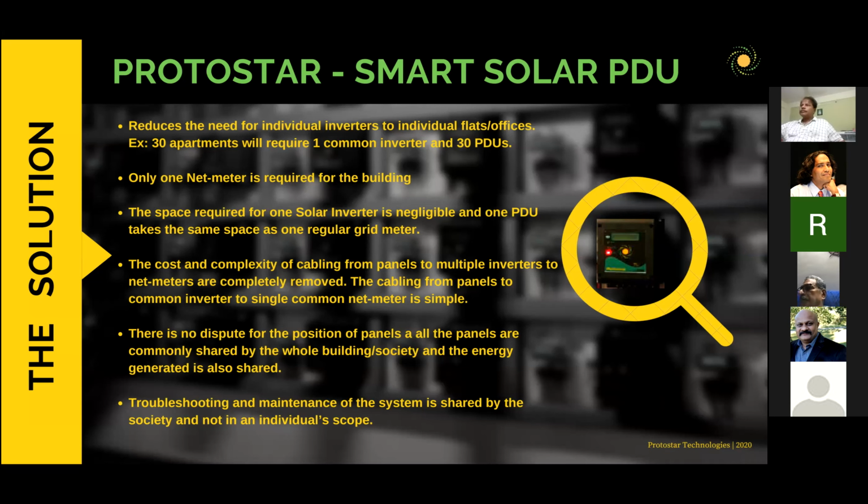So when you're initially on priority solar and then go to MSEB, it drops you down a slab. Let's assume you use 200 units a month, every month, and you're getting 100 units from solar. Your top 100 units, which would be in the more expensive 100 to 300 slab, are taken out of that slab. So you end up saving a lot more money because of this, right?